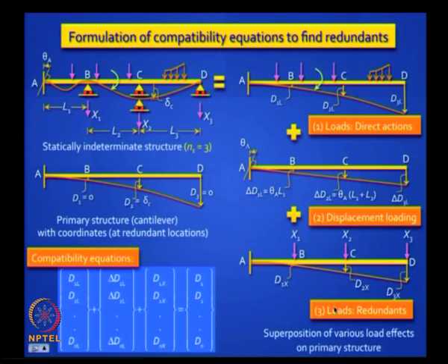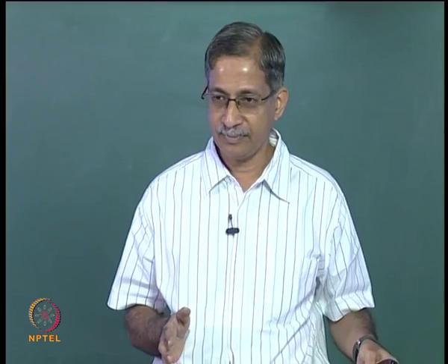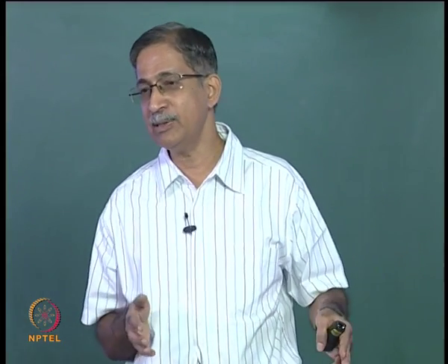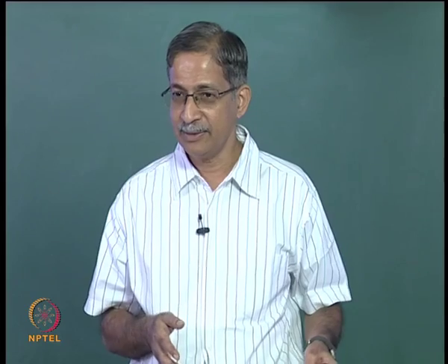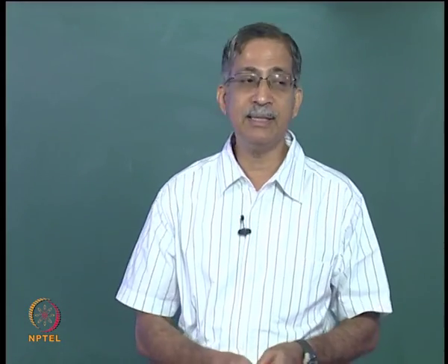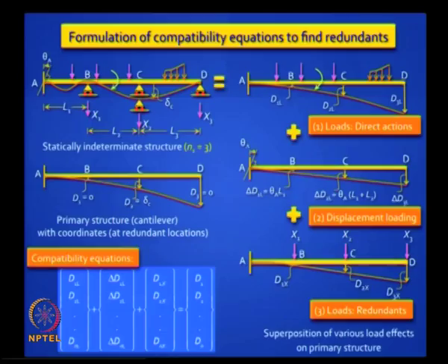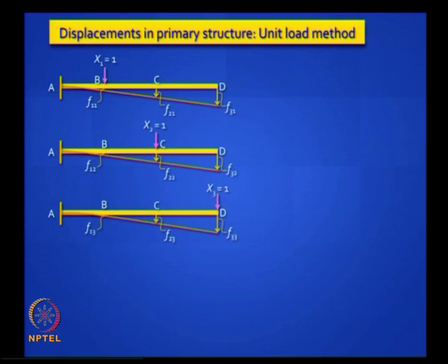Now you see how your learning has progressed. You first studied force response in statically determinate structures. Then you studied displacement response in statically determinate structures, and you need that understanding to write these expressions in the compatibility equation, because you are still dealing with a statically determinate primary structure. Now you will find it convenient to apply one load at a time according to the unit load method. Now you are familiar with the definition of flexibility.